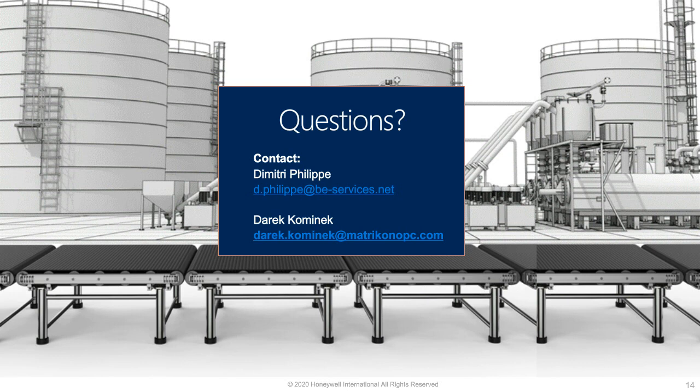This one, how about Matrikon support with Allen Bradley PLC and Rockwell RSLinx runtime? The way the question is phrased sounds like it's more about how you establish connectivity as an end user. That's more towards the connectivity products that Matrikon has, the ability to connect and convert that data from that environment into OPC UA. So things like our connectivity drivers, or UA Tunneler, which does the conversions between Classic and OPC UA. That's where that would sit.